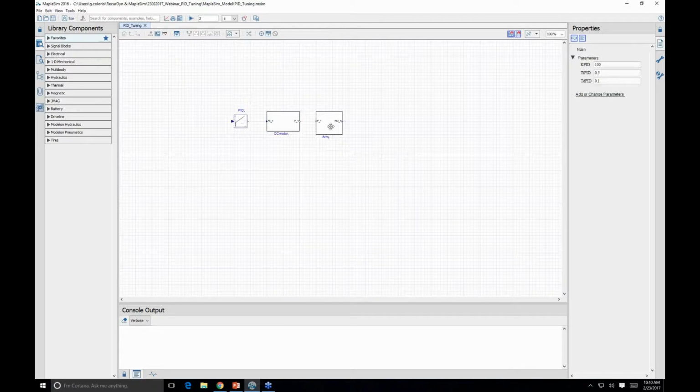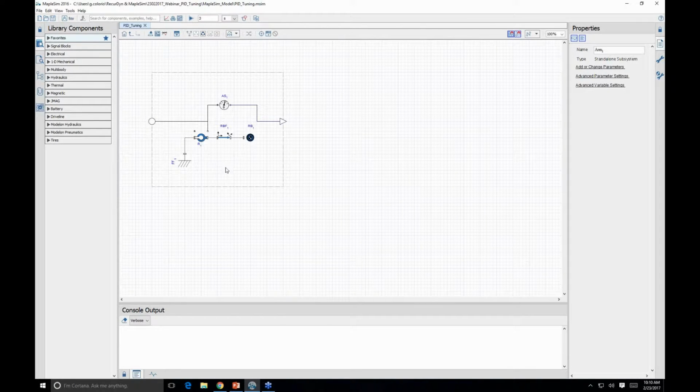So this is the arm instead. The arm is formed by a reference frame, a revolute joint, a beam, a mass on the top of it, and an angular sensor, which is going to read the angle assumed by our beam and pass it to the control system.